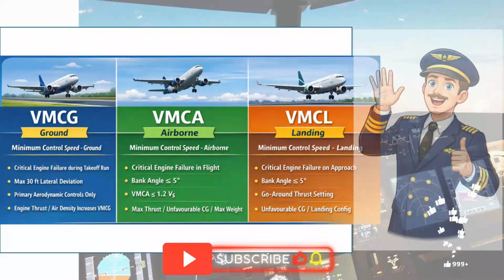Next, VMCA. VMCA is the minimum control speed in the air. It represents the lowest speed at which the aircraft can maintain directional control after engine failure, with a bank angle not exceeding 5 degrees. VMCA must not exceed 1.2 times stall speed, and is determined with maximum thrust, unfavorable center of gravity, and negligible ground effect.